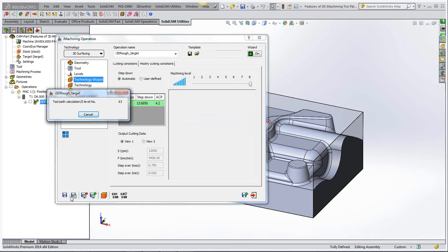and you'll see what a huge difference that can mean to the machining time. The aggressiveness of the tool engaging with the part, as it ramps in there, it can engage with the material at a larger angle, meaning that your chip control is going to be a more aggressive cut, and it will just go at it with a bit more gusto.